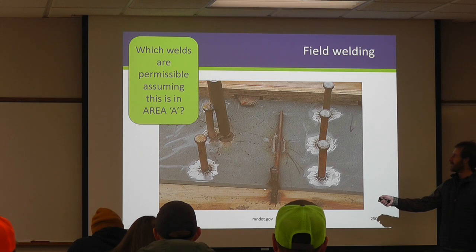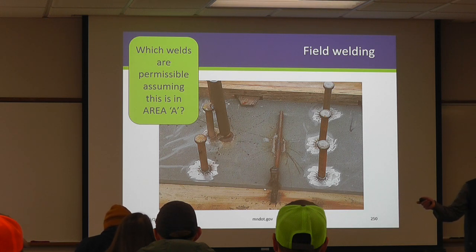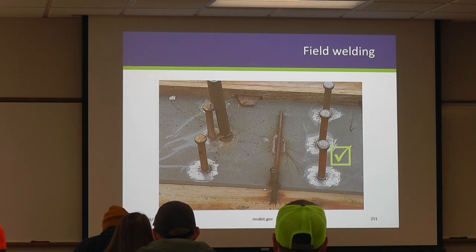No. How about your overhang bracket? Coil rod, right. None of these are permissible in area A. The contractor has to come up with a different way of attaching their supports to the bridge, even outside of area A.